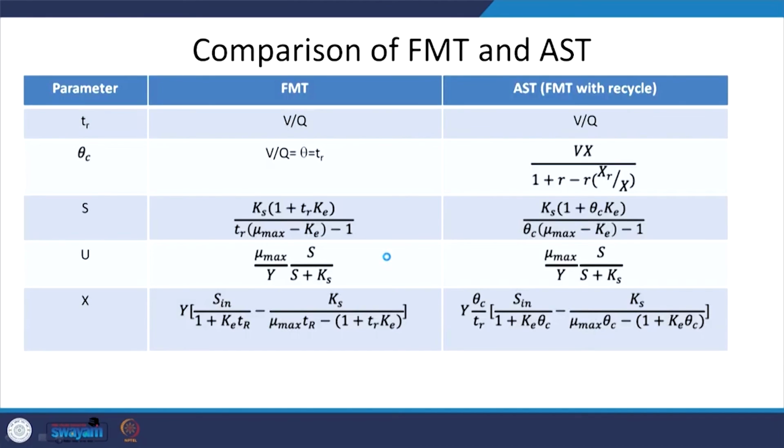Here, from the MIT OpenCourseWare, we have a comparison between a fully mixed tank. This is with recycle, what we looked at, and this is another case without recycle, but we will usually not look at this practically. So, theta, or retention time, is V by Q obviously. Theta C: if I do not have the recycle, whatever is coming in is going out, and the microbes are not spending any additional time because there is no recycle. So, theta C will be equal to V by Q. But if I have recycle, obviously the theta will increase, right.